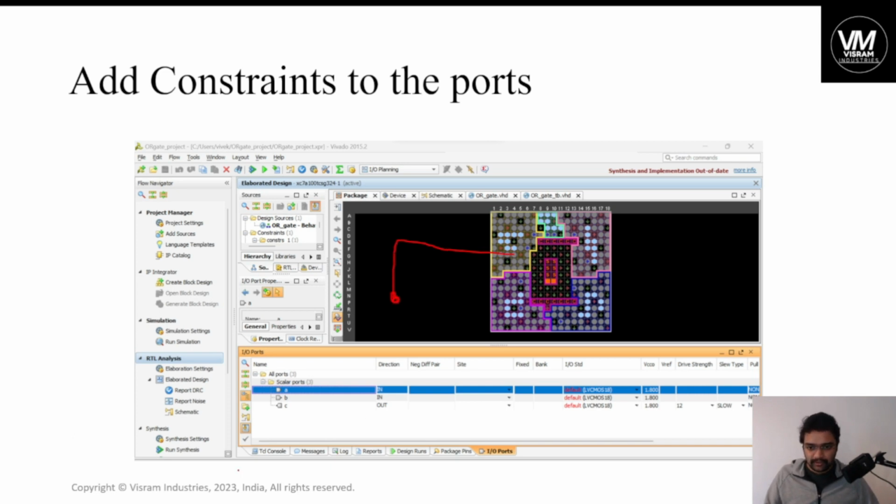I can show you. So this LED is connected to the pin of this. And how do you enable? This might be M16. Let us call this M16. So in this column M16, one pin is connected to the LED, but we need to enable it. How do we enable? From the OR gate.